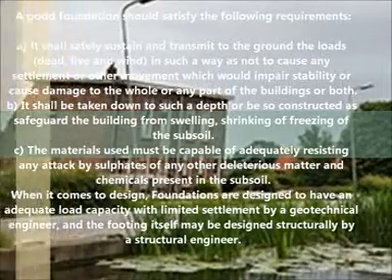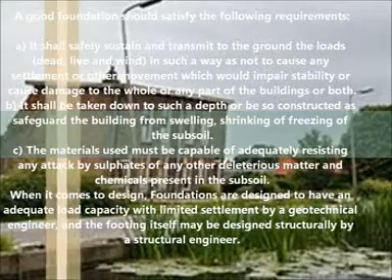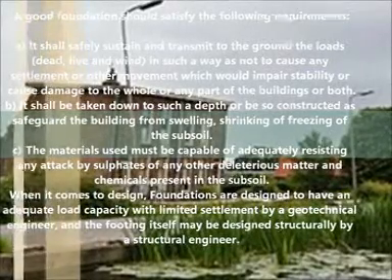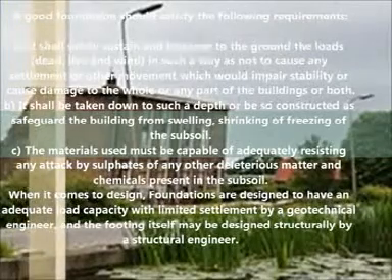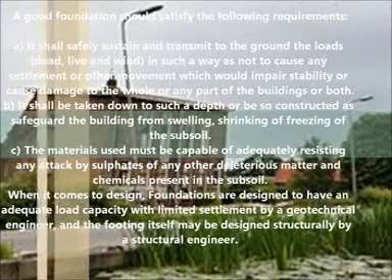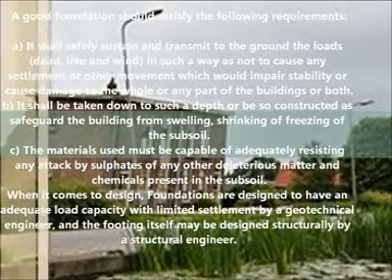B. It shall be taken down to such a depth, or be so constructed as to safeguard the building from swelling, shrinking or freezing of the subsoil. C. The materials used must be capable of adequately resisting any attack by sulfates or any other deleterious matter and chemicals present in the subsoil.